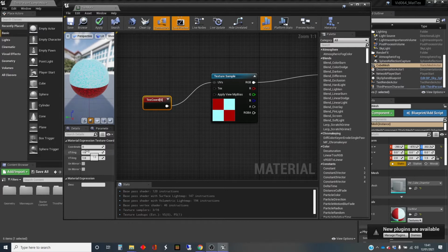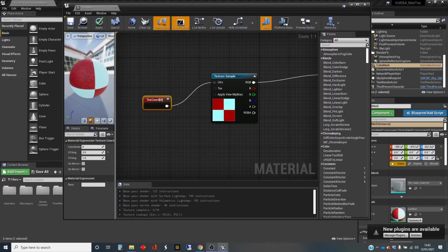we've got some useful bits of information. If we want to do U-tiling and V-tiling, that means we want to make the texture smaller so that it gets to the edge of the texture and then redraws it. It's called tiling, putting more than one version of the texture on. Then we change these numbers here, and the U-tiling is, in terms of the texture as a square object, from left to right, and the V-tiling is up and down. So if we increase the U-tiling to 3, then they should now become rectangles.